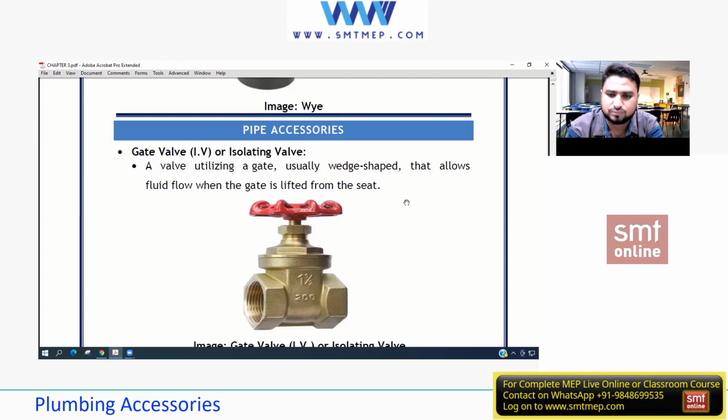Yes, so likewise, as you said just now, if you observe this, you'll see different valves nearby to the toilet. That means I can cut down the water supply in this area and we can go for the maintenance. So always remember, this will always be open whenever we need it. At that time only we'll be closing this, isn't it? So completely open and completely closed.